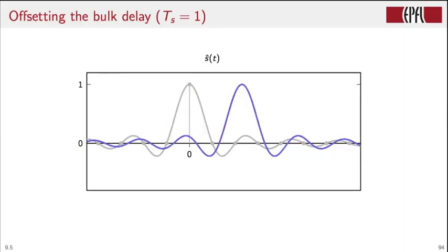This signal gets transmitted over the channel, and it gets to the receiver after a delay d that we can estimate, for instance, by looking at the displacement of the peak of the interpolation function. The receiver converts this into a discrete time sequence. Now in the figure here, it looks as if the sampling instants at the transmitter and receiver are perfectly aligned. Now this is not necessarily the case because the starting time for the interpolator at the transmitter and the sampler at the receiver are not necessarily synchronous. But any difference in starting time can be integrated into the propagation delay as long as the sampling periods are the same.